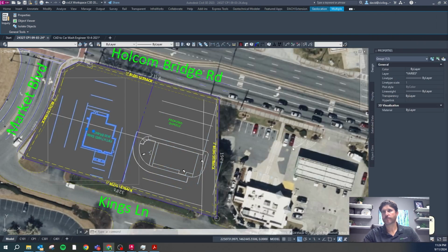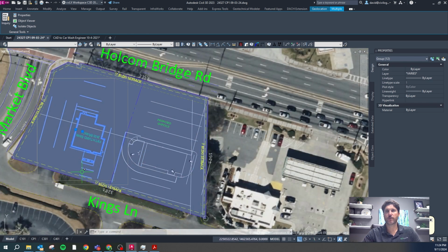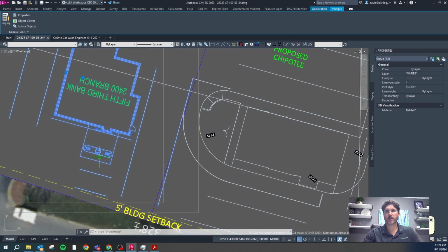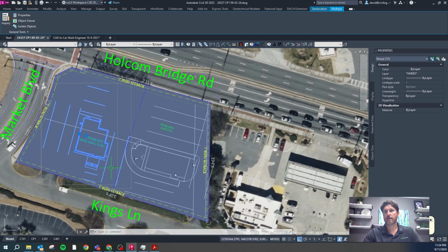So you can see that's what I did. Here's that green space that was in that picture, parking, drive aisle, and then the drive-through is on this other side. I offset this by 12 feet because I know a car is going to pull in there, and then I left another 12 feet for bypass. I need to be able to get cars through here, and I'd like them to be able to get out here too. This is the drive-through, so people might drive this way, so I just did a 24-foot drive aisle. Now I had to squeeze this in.